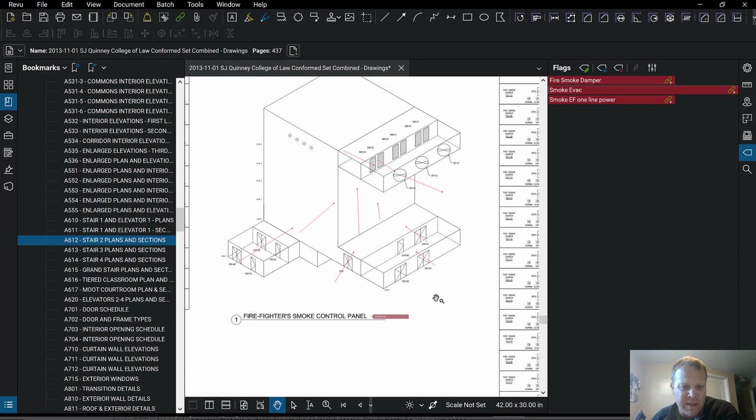Let's try and put this in sequence. Let's do doors, dampers, and exhaust fans. Okay, we got all that. Those are all working really well. In fact, prior to doing any of that, we probably have to turn and bump each individual motor on all these fans, make sure that they're running individually, and then move to the next stage.